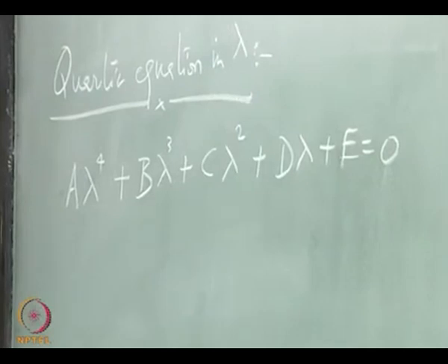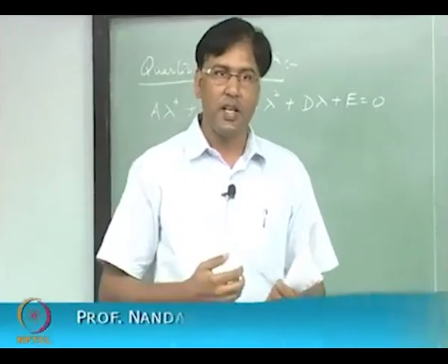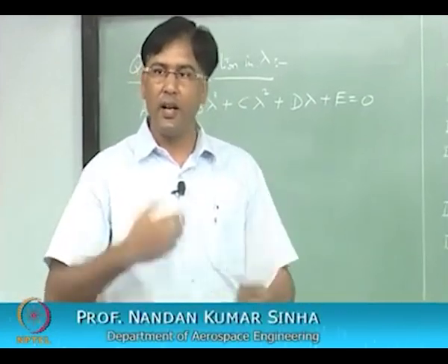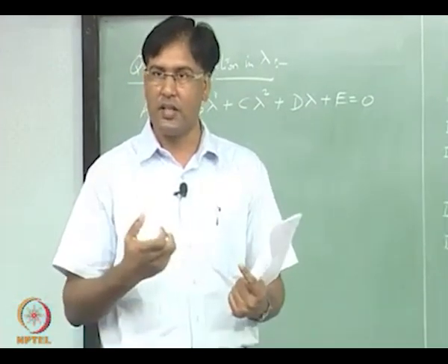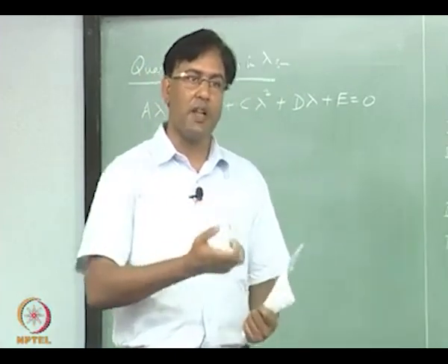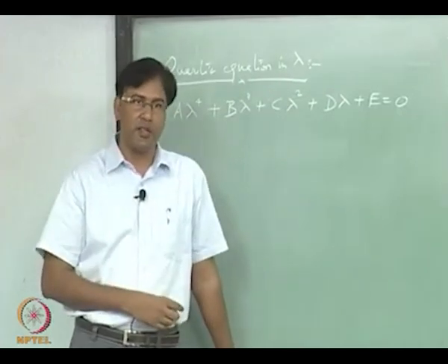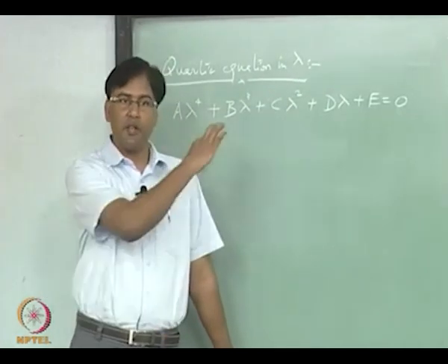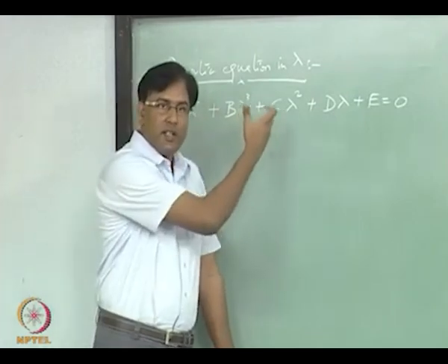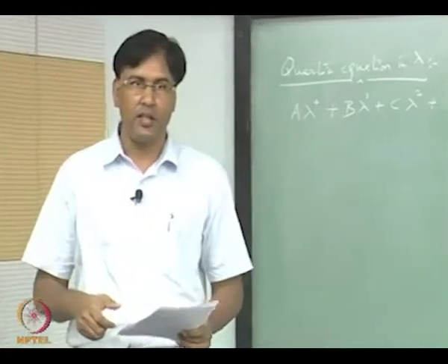See, you can arrive at a number only when the numbers are known of the parameters, but let us say I am at a stage where I cannot give any numbers to those parameters, right. For example, Cm alpha, if I do not want to give any number to that, but I want to look at how Cm alpha is going to affect the stability of the aircraft, right, then we have to work with these equations in their full form without giving them any number.